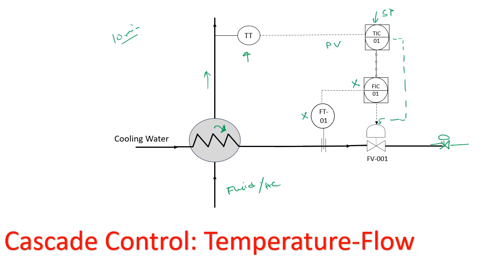In that situation, what is the parameter that gets impacted first? It is the flow. Again, your flow gets impacted first and much before your temperature, right? So that is why the process designer takes this flow as a secondary loop to this master loop. So here it is the master and this is the slave loop, and they have this connection here. So the output of this one becomes, if it is PV1, SP1, MV1, this becomes SP2, this flow becomes PV2, and this becomes MV2, right?